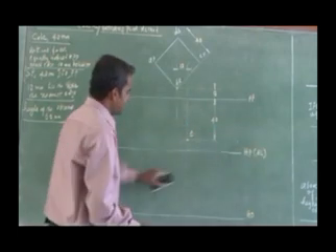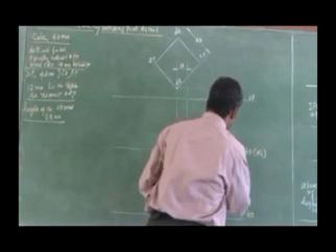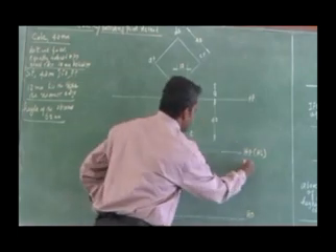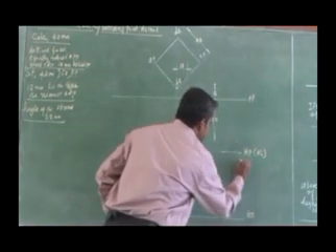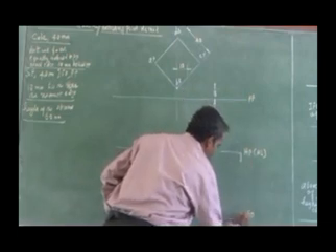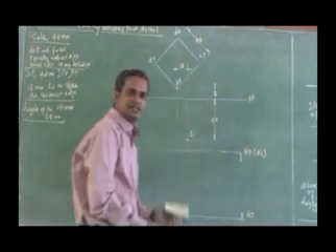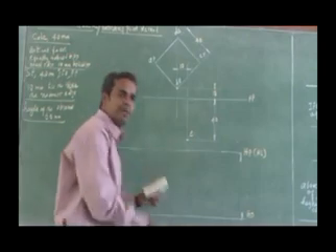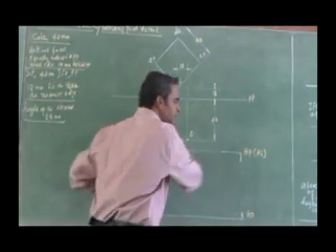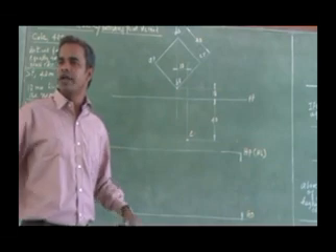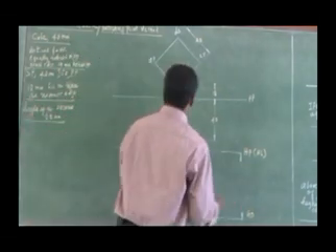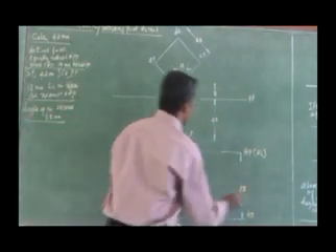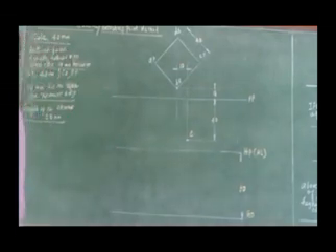Right. So what is the height of this line? It is 60. The height of the observer, or the height of the station point above the ground, is nothing but the horizontal line. I have to draw it. So that is 60 mm. Right. So you have to do this.